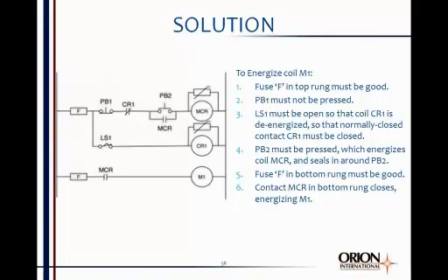Now, another thing that has to happen to energize M1 is I have to push button PB2. As soon as I push button PB2, it will energize this MCR, Master Control Relay is what that stands for. When that energizes, it will close this seal in.